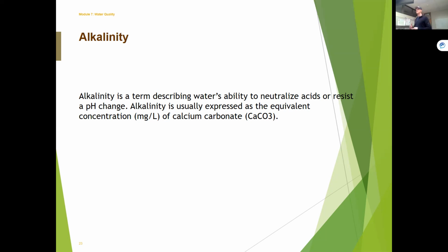One thing they use is a measurement tool called an LSI, and I think we touch on it later. That stands for Langelier Saturation Index. It's a measure of how aggressive or corrosive a water is, or whether it is scale forming. I always like a little bit of calcium carbonate, and I like a little bit of scale forming, so that we're not running into issues with pipes being damaged due to aggression.